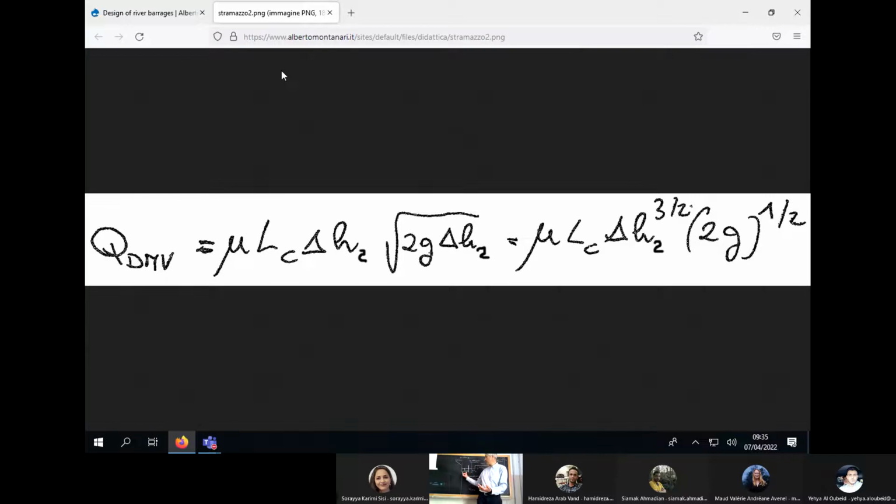If we reduce the width too much, it is a bit concerning for two reasons. One reason is purely, let's say, not technical, and is the fact that the environmental flow spillway can get stuck by floating material. If the environmental flow spillway is too shrinked, floating material can create obstructions. So this is a non-technical reason.